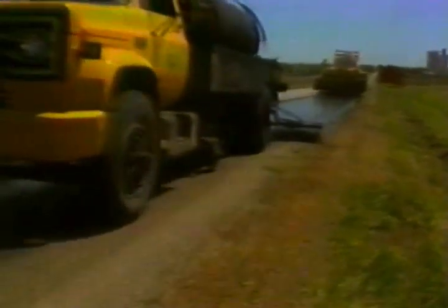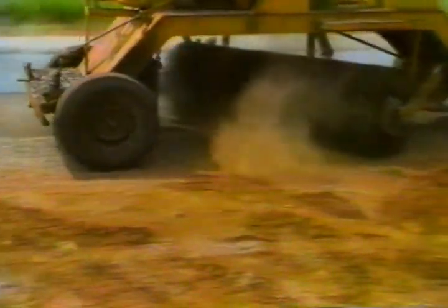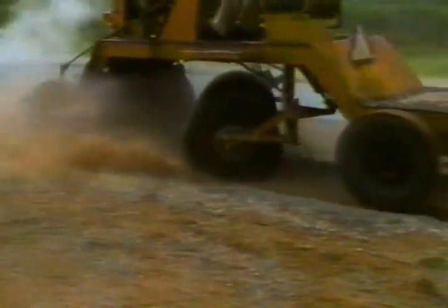Improper equipment operation is responsible for many problems, nearly all related to the fresh binder. A careless broom operator may do more harm than good when trying to clean the road shoulder too near to the distributor, especially if the wind is blowing in the wrong direction.